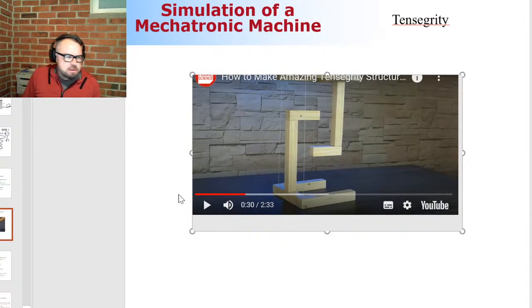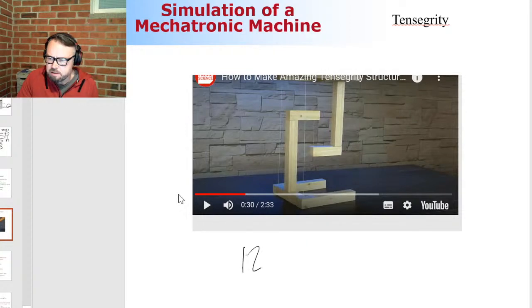Now, degrees of freedom in this system, when we're looking at this from the mathematical perspective, is such that we have two rigid bodies, and they are spatial bodies, three-dimensional bodies. You know that a spatial body has 6 degrees of freedom, so it can move in 6 different ways. Okay, now that's a total of 12 coordinates.